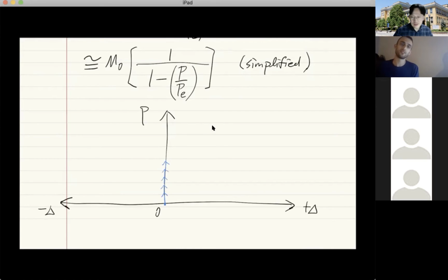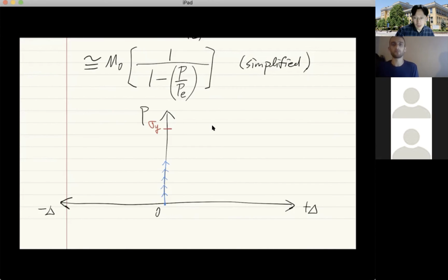Now, there are lots of things in structural stability that we can do. In this particular approach, or my approach, we are interested in finding what will be the level of force that would let the structure fail without reaching its material strength. Because if it's a ductile material, you understand that there's a sigma y here, right? And suppose it's a concrete, you may call it f prime c, somewhere here. Of course, f prime c must be much lower than sigma y because concrete is considered much weaker. So you can imagine there's an f prime c here for concrete.